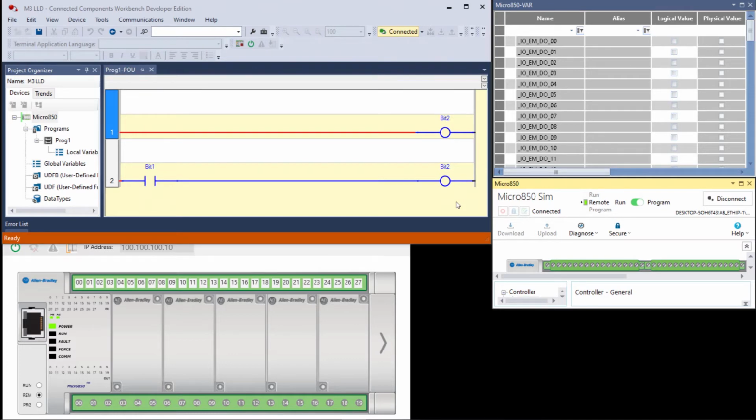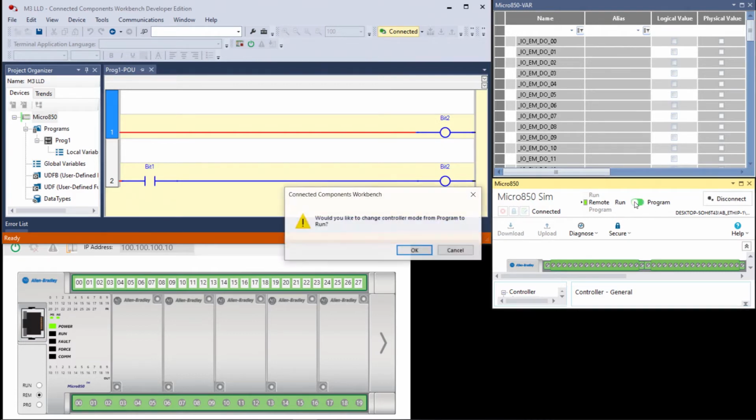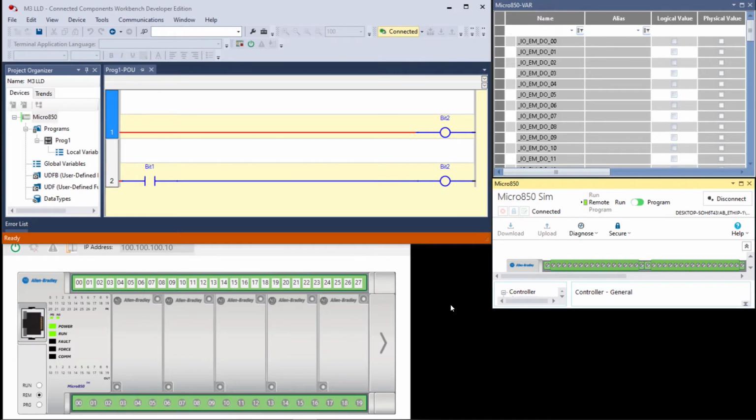While watching the output on rung 1, which is bit 2, switch the controller to the run mode, and we'll do that over here, run mode. And you notice nothing changes. We switched it to the run mode. Is rung 1 true? Yes, it is. It's unconditionally true.